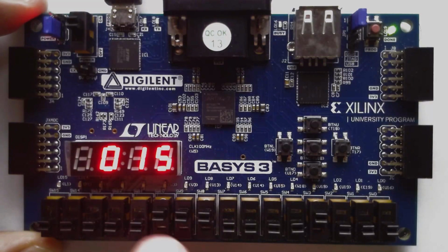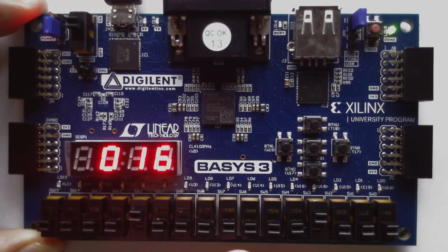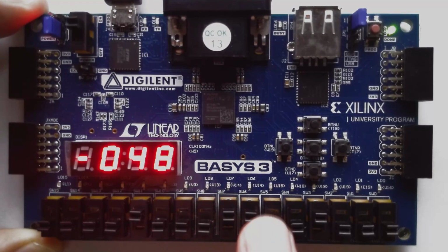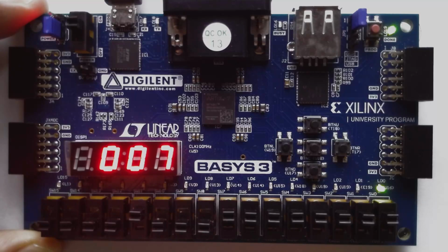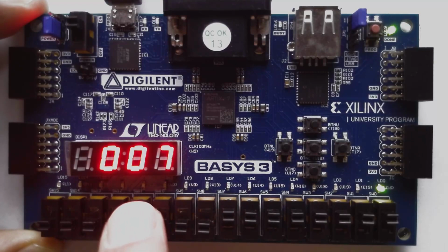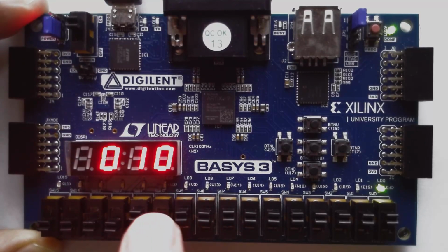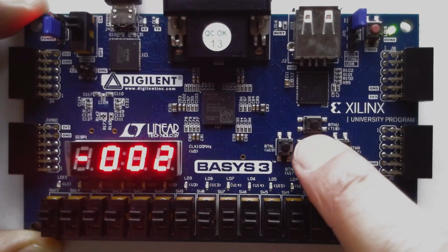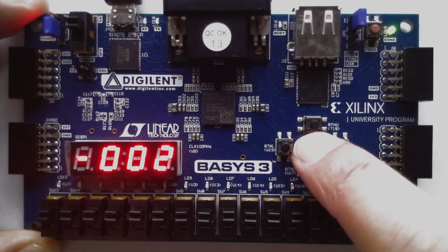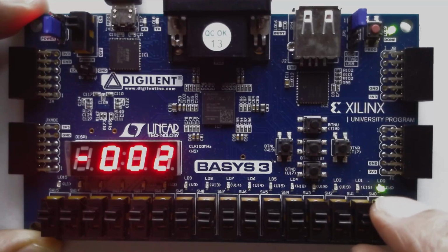Now if I just do 8 here, I can also switch all of these on. And I've sign extended the number here. That means that when I set this to a 1, it will extend all those ones out. So I'm actually dealing with a 32-bit number. So all 1s, you might recall from 2's complement, is actually -1. So I'm adding -1 to 8 here. If I set them all to -1, we get -1 plus -1. I've set the button in the middle here to change the mode to subtract. So if I press that, we get -1 minus -1 is 0. So this all seems to be working.